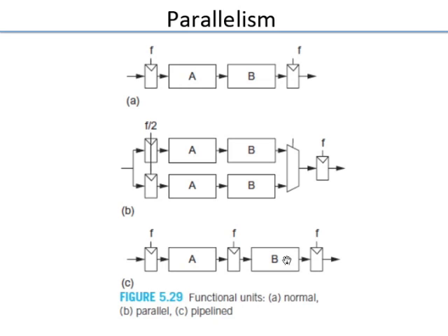Parallelism could also be temporal parallelism, which means you are pipelining it. Pipelining is also a kind of parallelism because A and B are running in parallel. You can do pipelining and parallelism both simultaneously. This is one very important technique which you are already seeing in industry. That's why people talk of multi-core, because you push performance by having more things running in parallel, so that each one can run at a lower frequency and the corresponding voltage is also used, so that you are at the lowest power point for that particular core.